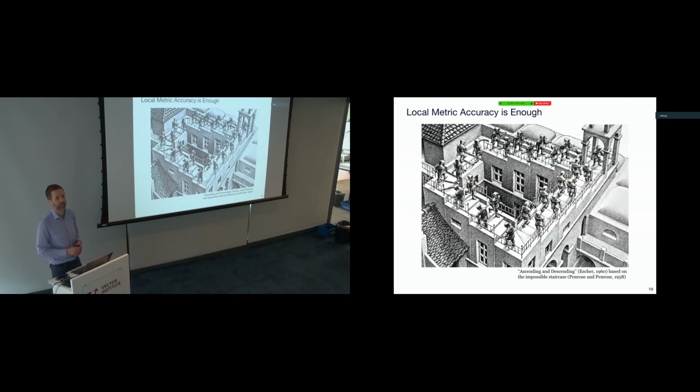And the same thing is true in our map, actually. I showed you some paths that are actually closed loops. We actually make no attempt to make the local transforms add up to identity transform around that loop. It just doesn't matter to us. We just tell the robot, if we come back to a place we've been before, this is the same place. Put an identity transform between these two poses, but it doesn't have to add up to identity transform all the way around the loop. And that's good enough to let the robot actually make local decisions in order to drive on the path.